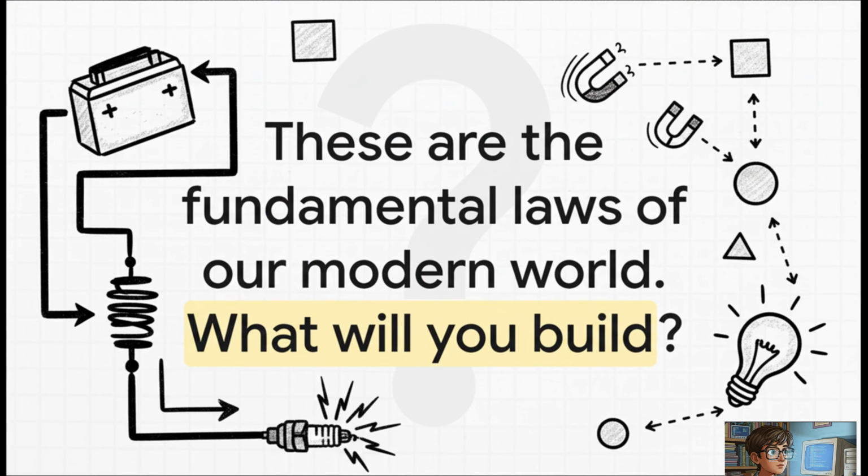So, let's close the loop. Let's solve our mystery. How does a little 12-volt battery create thousands of volts? The secret sauce is the inductor. Remember how it hates sudden changes? Okay, so the car's ignition system lets current from the battery flow, building up a ton of energy in the inductor's magnetic field. Then, right at the perfect moment, it suddenly cuts the power.